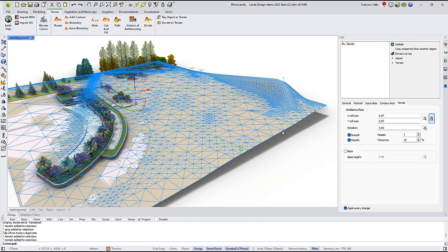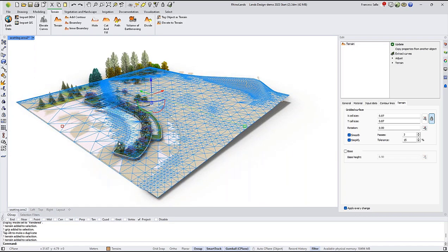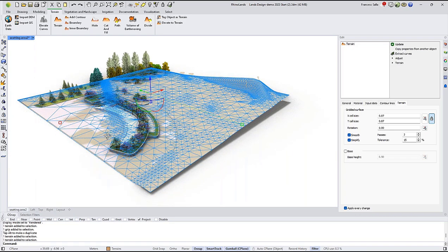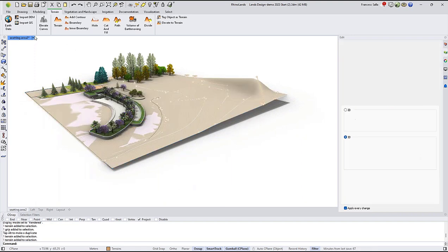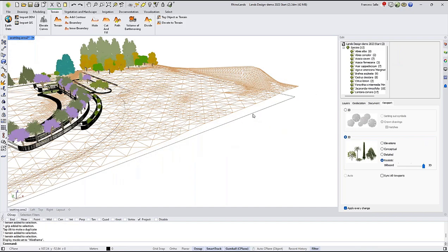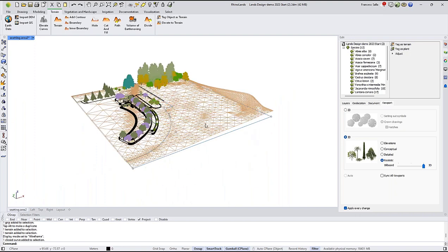Okay. All right. So the first thing I'm going to do, since I see that this area is overlapping with an existing surface or zone that I had underneath, so I'm just going to trim the terrain from an existing curve. I'm going to switch back to wireframe a second, because here I have a boundary curve that was previously created, but I'm going to use it to trim the terrain and define the new boundary for the terrain.